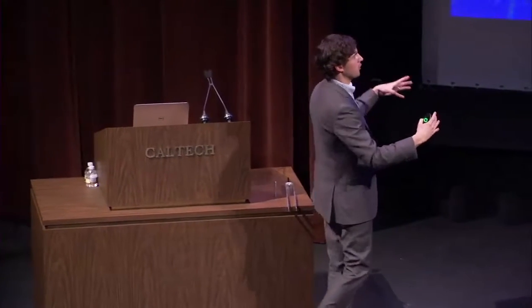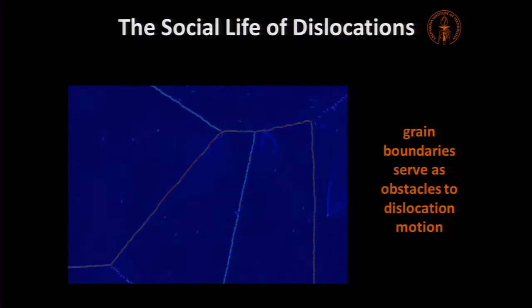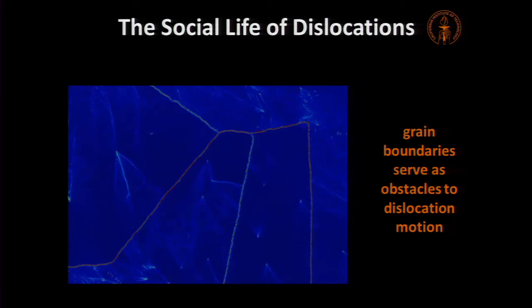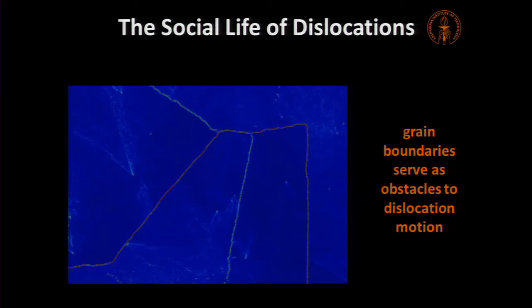Of course, this breaks down at a certain length scale, but in principle, if you make your grains smaller, dislocations can't travel that far anymore, which means you must apply more load to create new dislocations and to keep deforming the piece of material. Another way to make material stronger, which goes in the same direction, is by alloying.